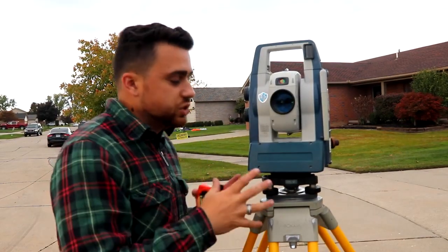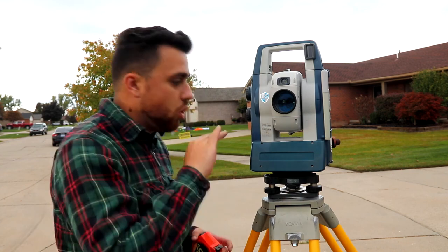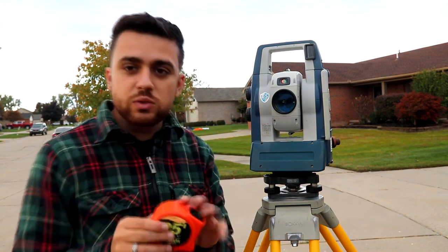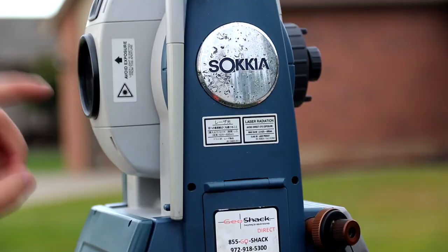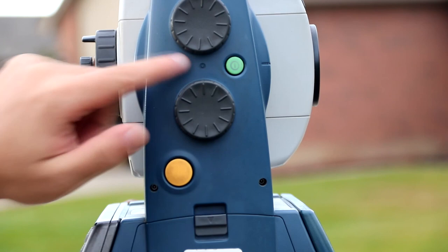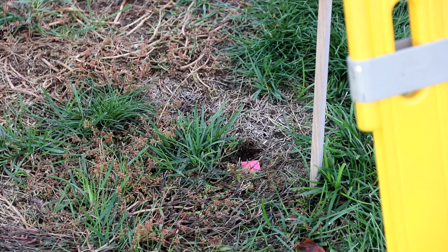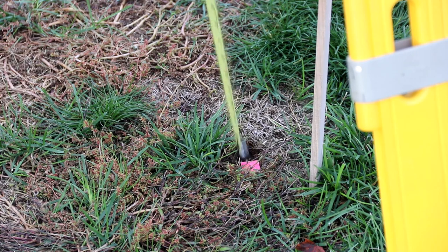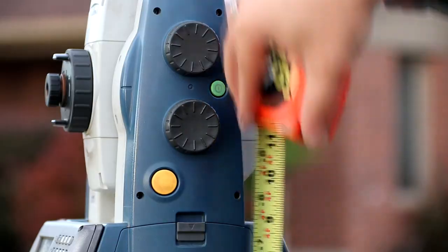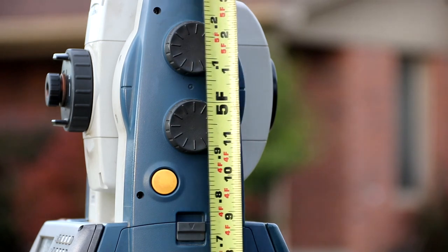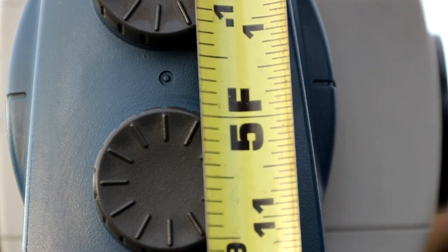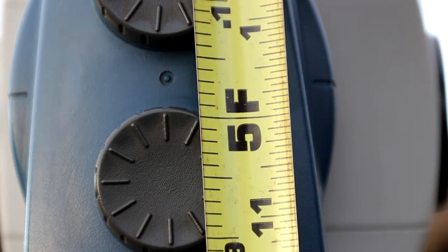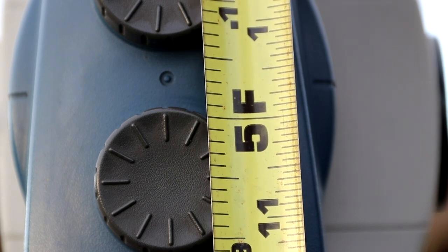Once you've leveled out your total station, let's go ahead and figure out how tall the instrument height is. The way we do that is by using this 25-foot tape. Simply pull and measure the height. Now you want to be measuring where this line of sight is. A lot of total stations will come with a dot that's implemented on the side right here. This is where you want to measure to. Now you want to start measuring by putting the tape all the way at the bottom of your point, and you're going to want to measure all the way up until you see where this point is at. And it looks like it's coming in at 5.05. So our instrument height from the point to our scope is 5.05.